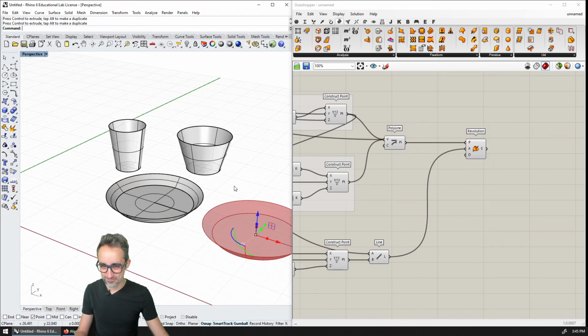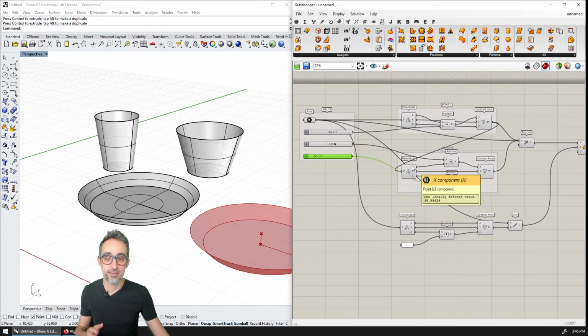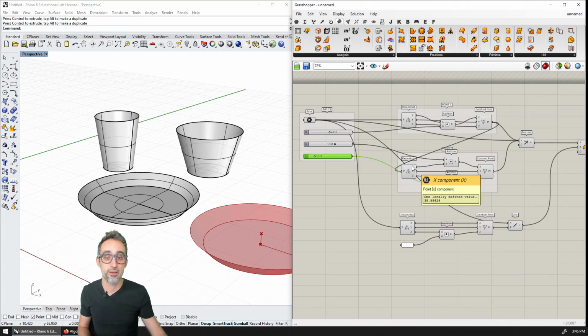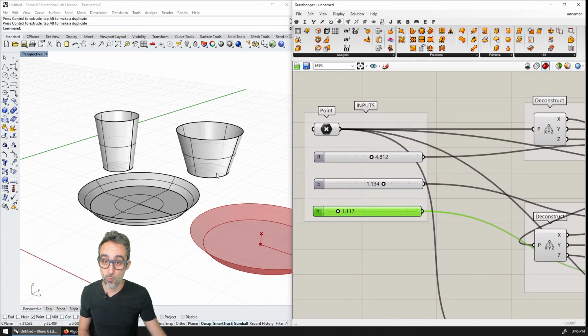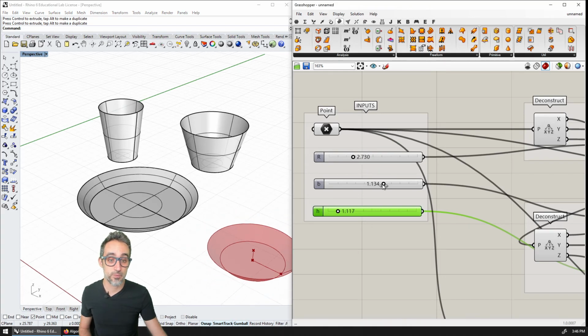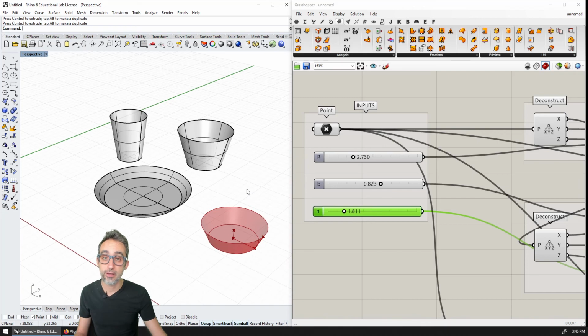And this that you're seeing here is what's very nice about parametric modeling. The idea that by creating the tree of relationships that define a particular family of forms, then by modifying the input parameters, like where the center of the glass is, and some numbers that define its parameters, its height, the width, etc., I can explore the family of possibilities that this gives me, in a parametric way.